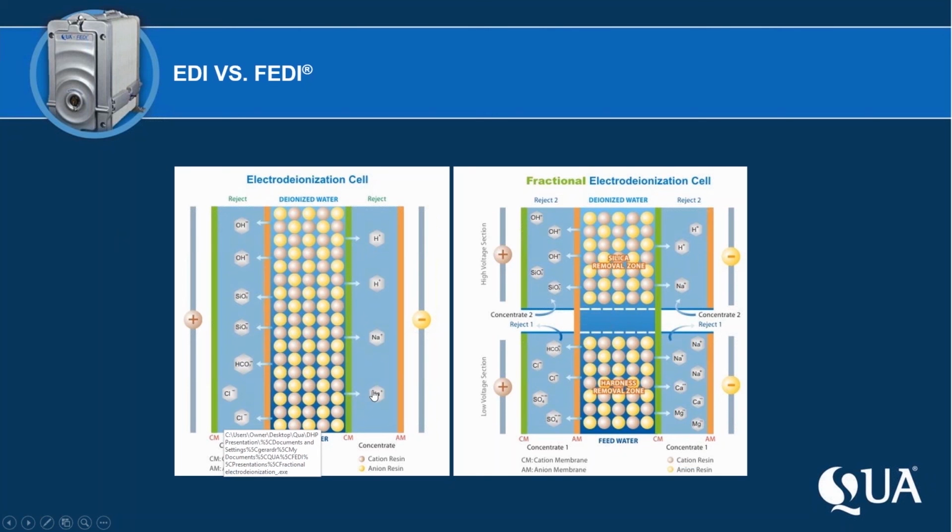When you split water in the EDI, you have these, I'll say, isolated pH areas. In the bulk solution, there might not be a bulk solution of a high pH and a low pH. You have certain regimes of it, and that's where the scale takes place. It's when the calcium and the magnesium come in contact with hydroxyl ions and higher alkalinity. If you're splitting CO2, typically what happens is CO2 goes to a carbonate form and becomes ionized. When you start combining hydroxyl ions and the carbonate, and you're bringing your calcium and your magnesium down into that zone, that's where you start having scaling problems.